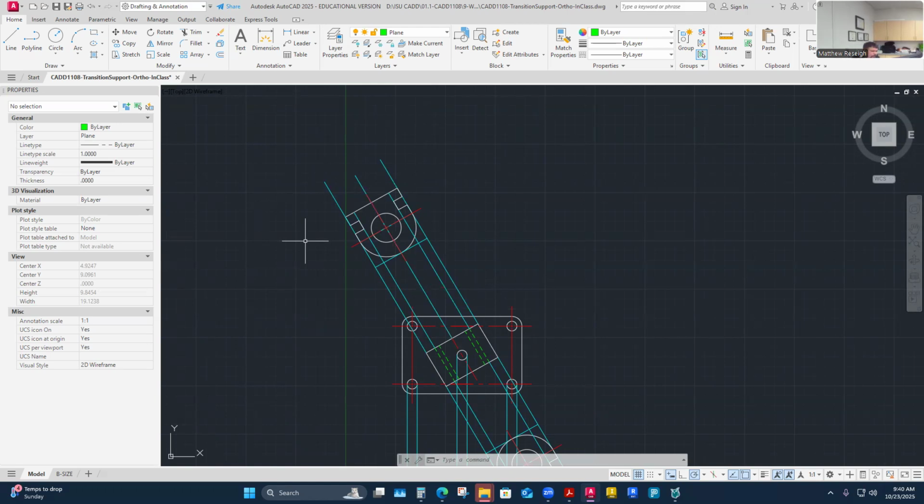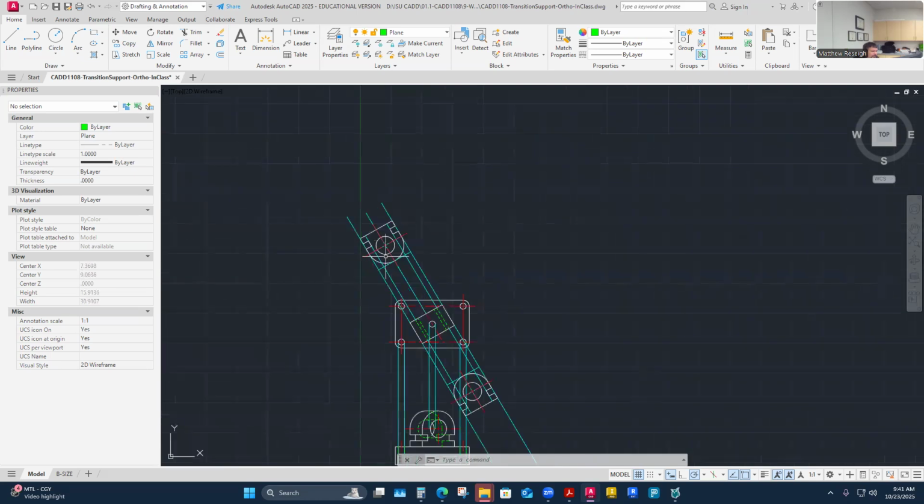And so with how labor intensive CAD can be, that's where I would forego full auxiliary views and do partials. But with a 3D program, it's actually easier. I mean, the program itself will pull the full auxiliary view. And you can still establish a partial auxiliary view as well with a 3D program. You just have a lot more control, and it's not so labor intensive to establish a full auxiliary view. So anyway, I was thinking about that.